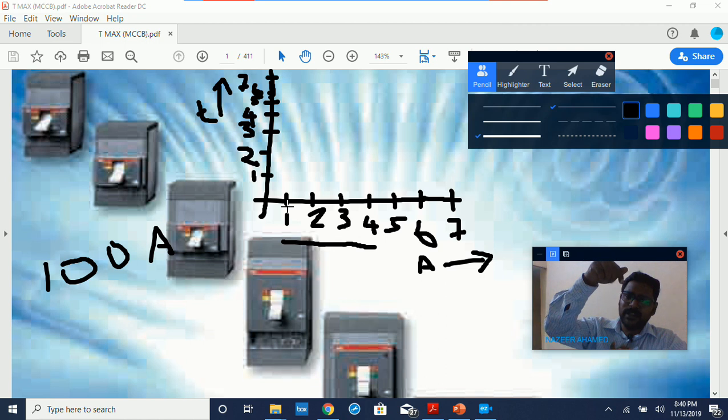Equal and opposite means that it will create an electromotive force 90 degrees in the top and opposite 90 degrees in the bottom. So this opposite reaction will make the disc rotate. I am speaking about the olden type energy meter which we use in our homes to measure power. We should remember, if you are using more power, the disc will rotate faster. If we use less power, the disc will rotate slower.